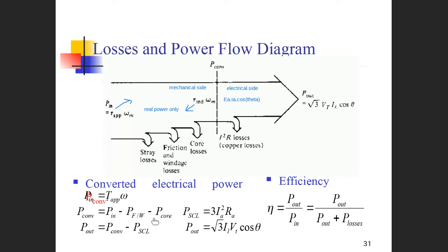Because here we do not show you the open circuit test with the mechanical input power. We do not show you that, but you should understand that when the mechanical input rotation speed is kept constant, then to overcome the friction, windage and core losses, you have to apply a small torque. This small torque is used to overcome the friction and core losses here.